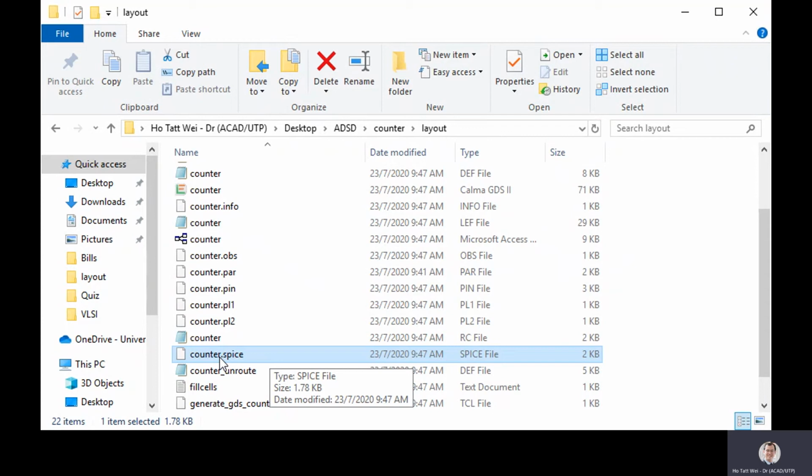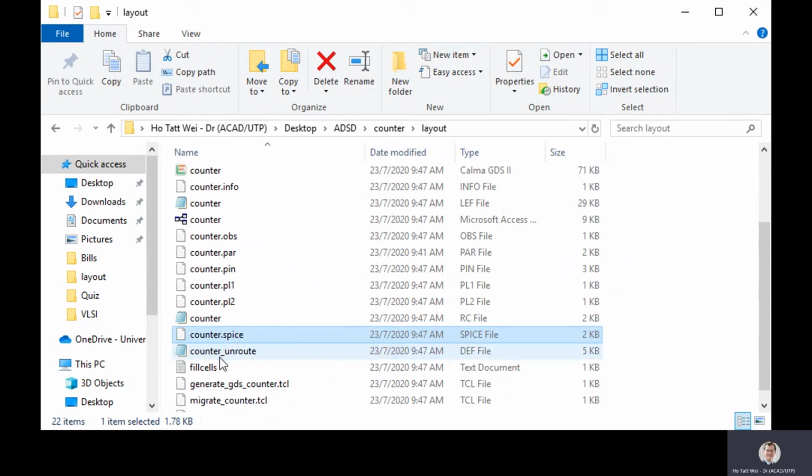As you can imagine, we do not do most of the verification work in SPICE, although in principle we could, because SPICE performs a much heavier computation. It solves differential equations on very fine-grained time steps, and this is a level of extraction that is much lower than what we need for the exhaustive functional verification that most designs obey.